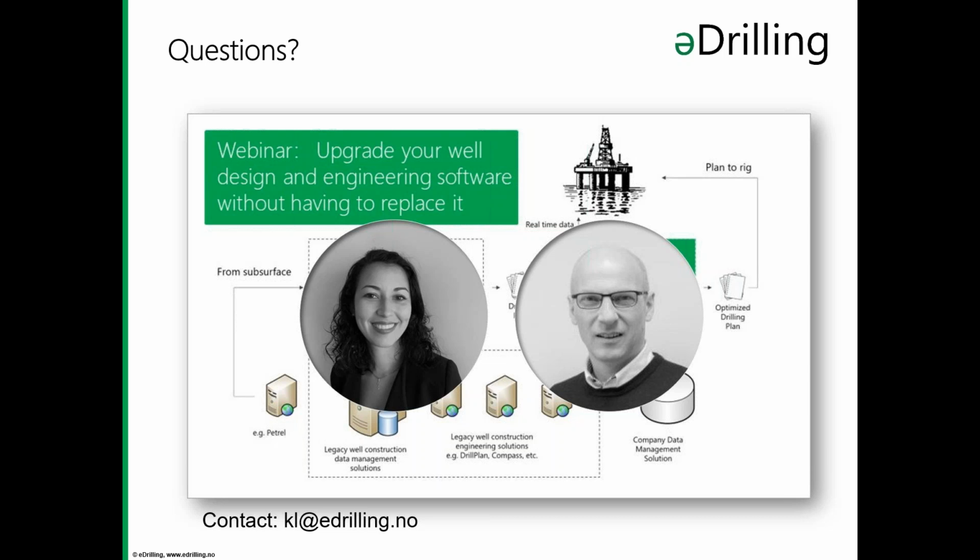I think we haven't answered the question before. How about cuttings generation? Is it based on ROP, formation strength, etc.? Yes, it is based on the ROP, the formation you're drilling in, of course, and also the cuttings concentration as moving upwards, depending, of course, on the mud and the rheology you have, and the cuttings slip velocity related to the flow that you have.